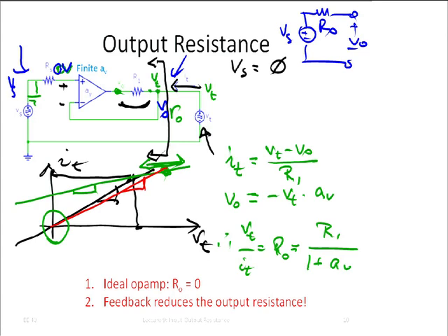For example, instead of having one operational amplifier that provides a gain of 1,000, I have two that each provide a gain of 30, and if I cascade them, I get 30 times 30, 900 gain. Things like that. Okay? Did I answer your question?